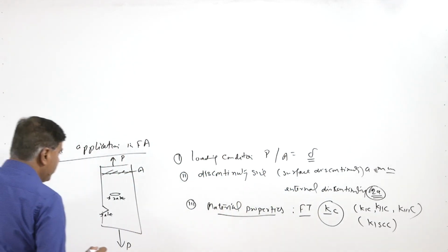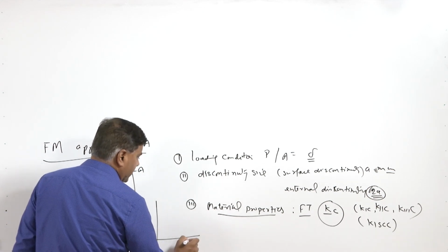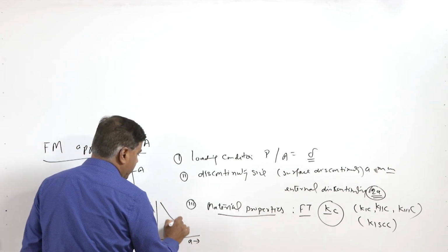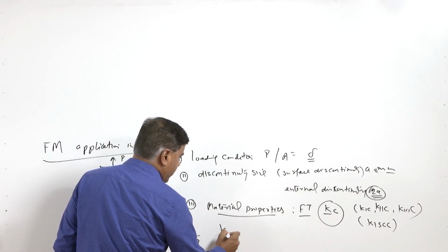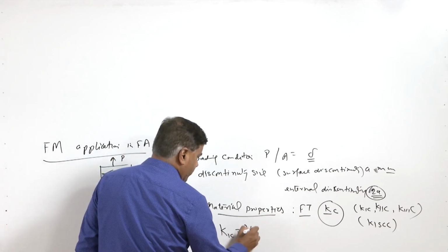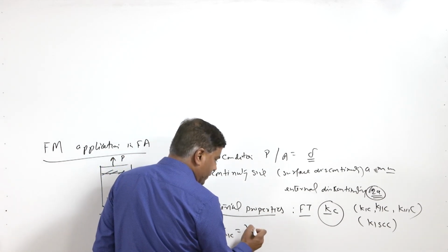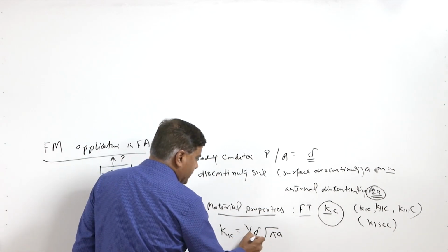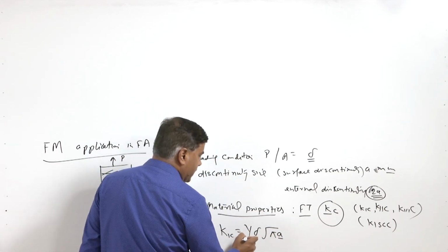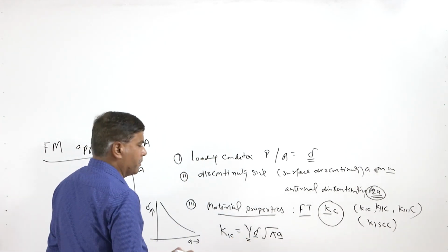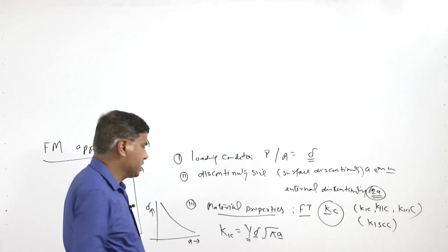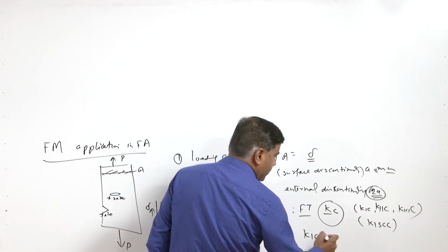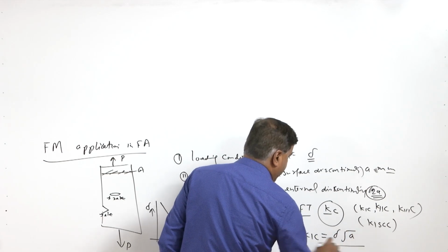We have already discussed the discontinuity size and the applied stress sigma. For failure resistance, they follow a particular relationship wherein K1C is given by a constant Y, which is a geometry related constant, times sigma root pi A. Sigma is the applied stress, A is the crack size or discontinuity size, and Y is the geometrical parameter, which in the case of thick sections and very wide sections is taken as 1. So, under simplified conditions, K1C is equal to sigma root pi A.